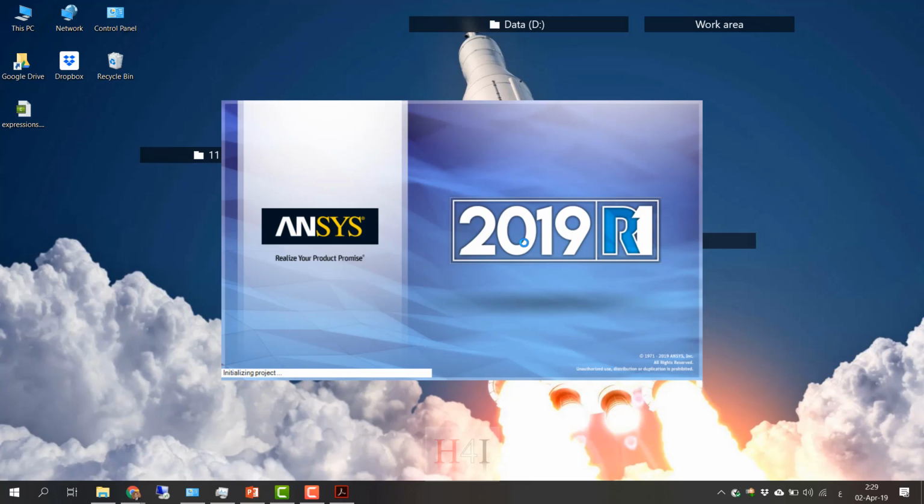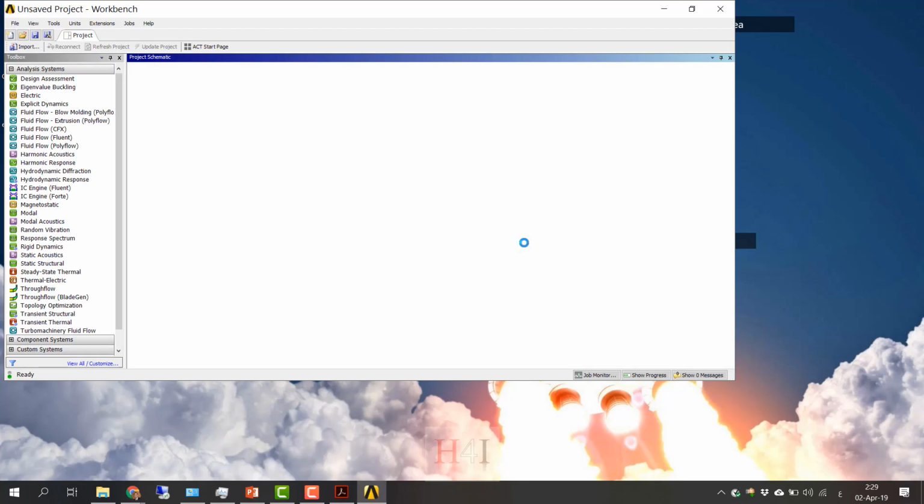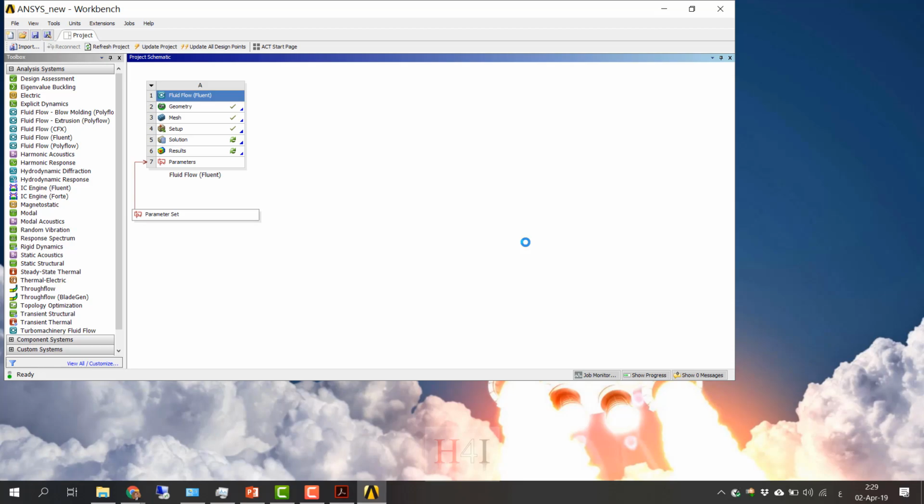You don't need it, but in my case, I have maybe 10 surfaces. Each surface has its own equation. In C++, I can define a way so that the UDF determines the equation for each surface automatically. So I don't have to enter the expression editor for each surface and define its equation, changing the equation 10 times for 10 surfaces. I've written a code which does this automatically. It can determine which surface it is and which equation it needs. Just change some numbers and continue.